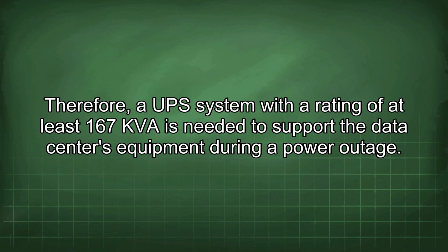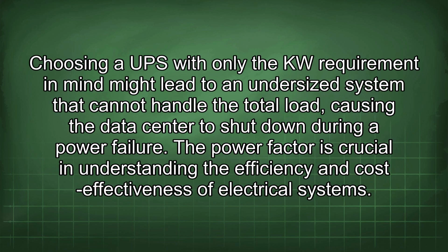Therefore, a UPS system with a rating of at least 167 kVA is needed to support the data center's equipment during a power outage. Choosing a UPS with only the KW requirement in mind might lead to an undersized system that cannot handle the total load, causing the data center to shut down during a power failure.